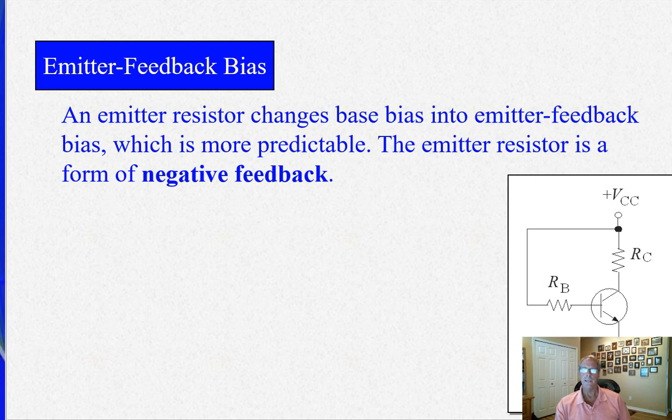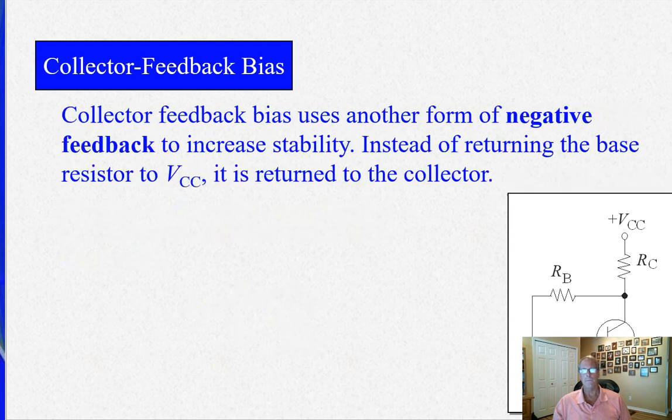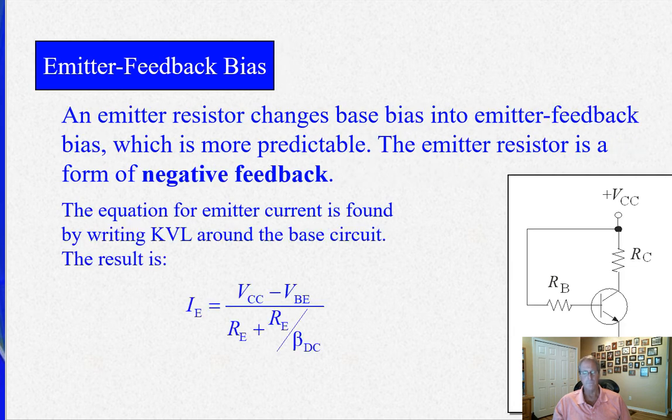And in fact, when we get further on, we'll see that all of the voltage divider bias amplifiers that we do have an emitter resistor in here for that very reason. It prevents something called thermal runaway, which we'll get into later in a different chapter. So again, they do the same KVL equation. On that, there's no difference, it's the same.